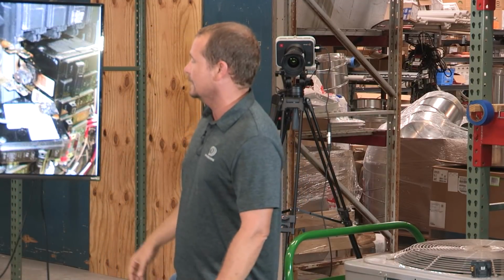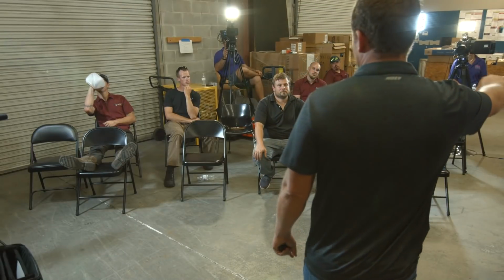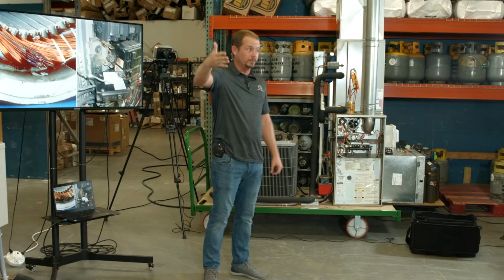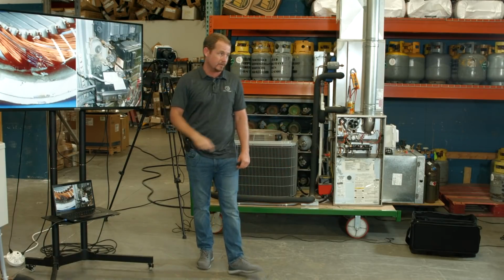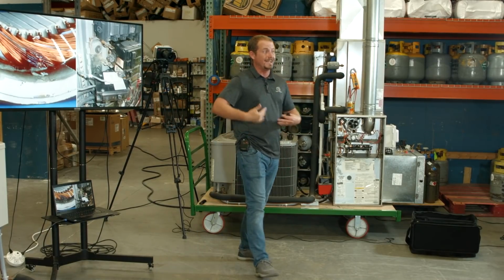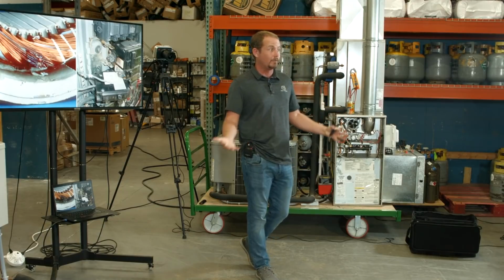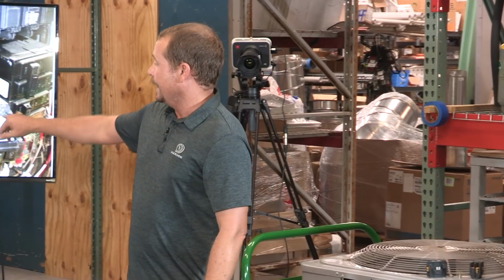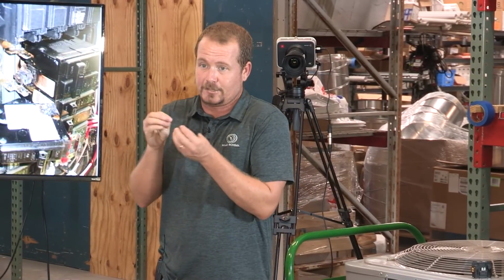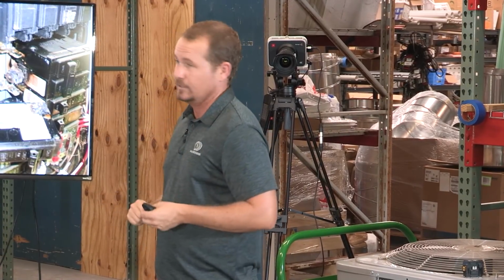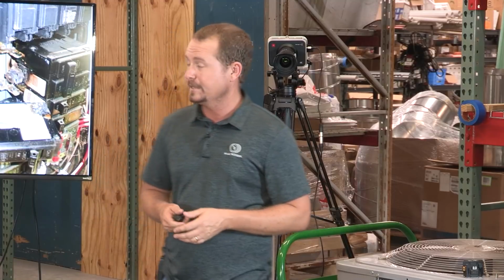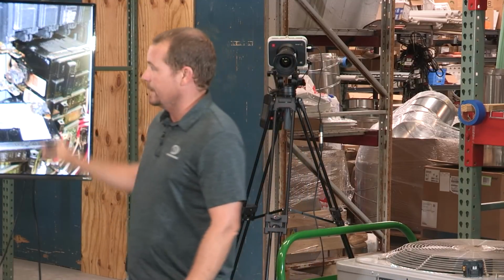Before this thing failed completely, whatever was connected to it had a pretty high voltage drop, almost assuredly, because you had resistance in the circuit, which is dropping the voltage, which is actually dropping the current. So whatever's connecting to it's not running well. Until eventually the surface contact size just gets smaller and smaller, heat gets more and more, until eventually it melts. Right? So making good metal-to-metal contact whenever you're making connections is key.